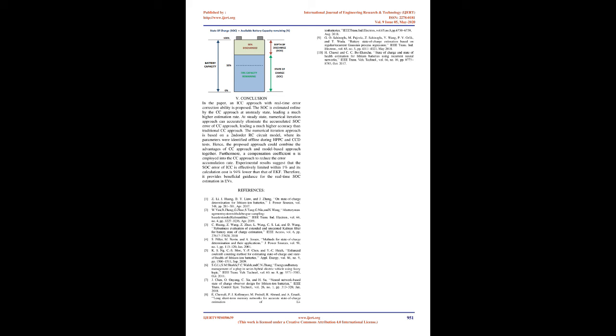The battery is exhausted when the loaded voltage, VB, becomes less than the lower limit, Vmin, during the discharging. In this case, the battery can no longer be used and should be recharged. At the same time, a recalibration to the SOH can be made by re-evaluating the SOH value by the accumulative DOD at the exhausted state.